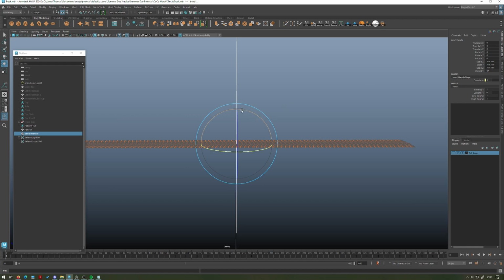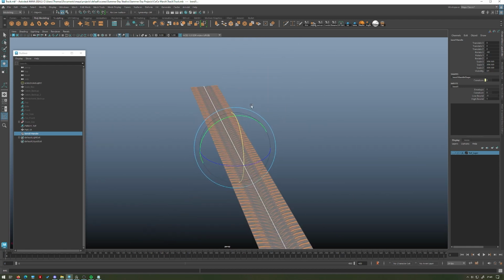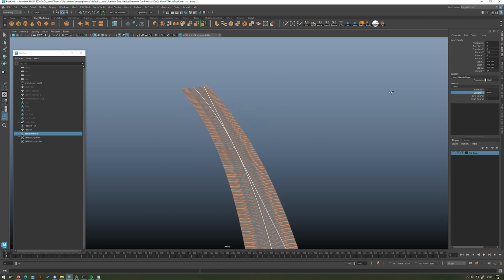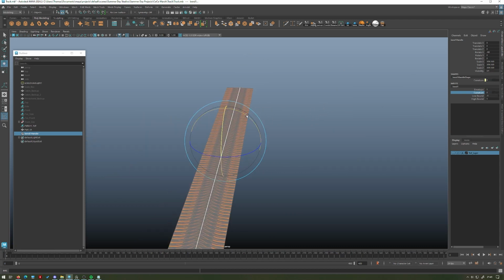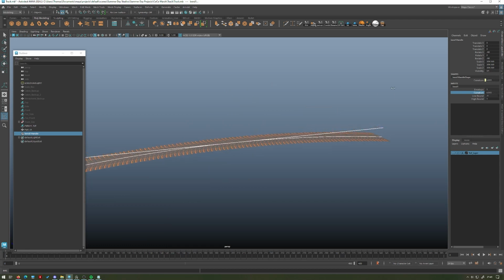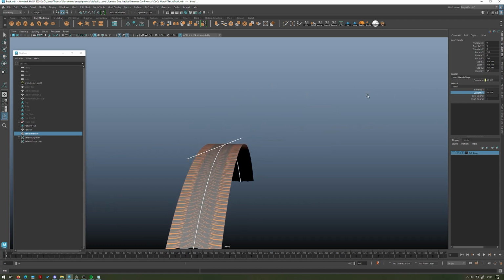So I'm going to rotate it. I'll hold down J in order to get that to snap to 15-degree increments, and that's then gone flat like this. To adjust the curvature, you can see here in the channel box editor, if I adjust this, it's going to adjust in the wrong direction. That's not going to work too well as a tire. It means we're also going to have to rotate it 90 degrees, whether it's minus or positive doesn't matter, in Z. Now if I start to rotate this, you can see it comes around like so.